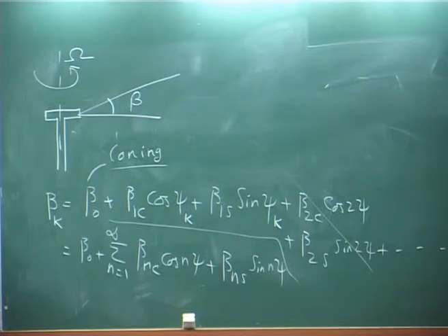So the rotor disc, now please understand, without this you cannot fly the helicopter, you need flap, because the flap is the one which is tilted. Your thrust vector, whatever is there, you tilt the thrust vector this way, then you fly forward. You tilt the thrust vector in the other direction, you fly that way, okay. The tilting of the thrust vector is obtained by flapping, okay.